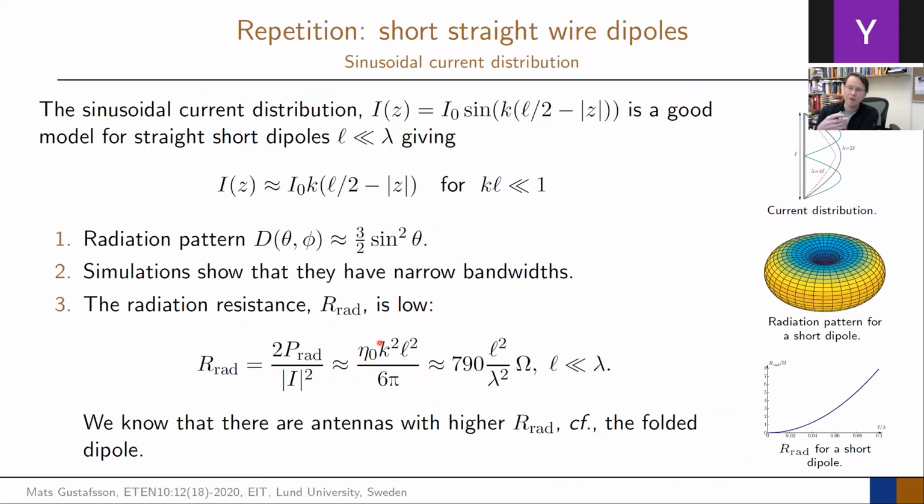The basic knowledge we get out of this is to go back to lecture 2, I think. There we looked at our dipole antenna, which is a resonance of half a wavelength. So this blue curve here, lambda is equal to 2L. When we shrank the size of it, we got a current that just looks like a triangular shape. It's losing this cosine type shape.